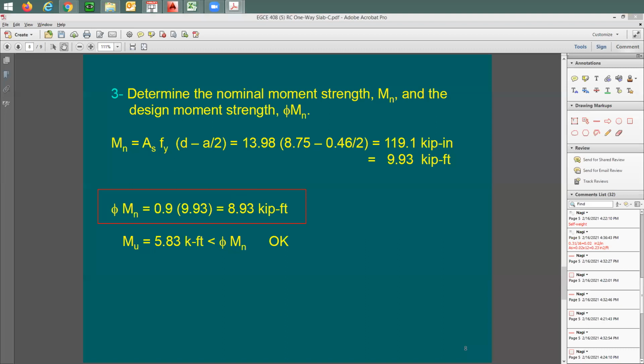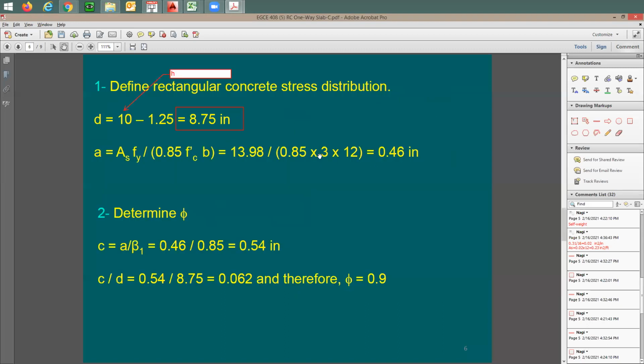And the question here says, and that is only for concrete slab. I guess you're talking about the concrete cover. So I'm going to say concrete cover for slabs is going to be 1 inch. So in order for you to figure out d based on h, you subtract 1.25 to 1.5. In beams, it's going to be about 2 inches, and you subtract maybe about 2.5 inches. Okay.